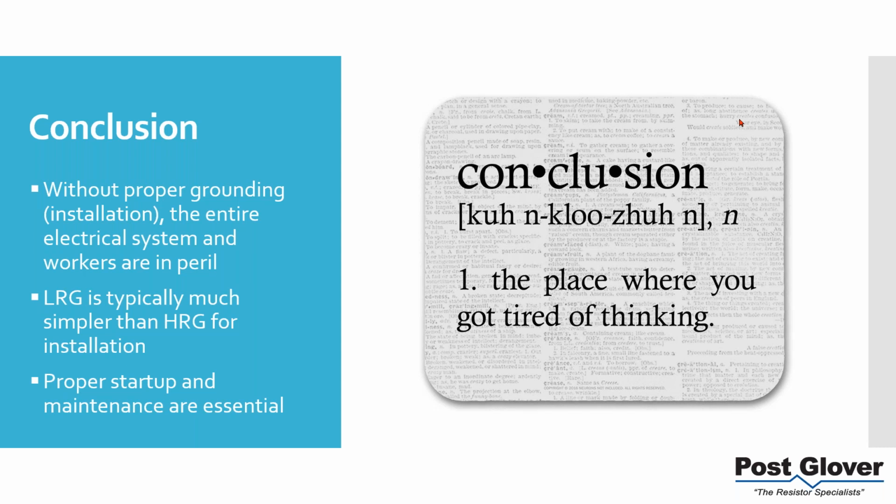We do it internally. To make a very simple version of it, we're measuring resistor current. We're measuring values across both the resistor and the test resistor, and we're basically taking what's left over and saying this is what the charge current is. I don't have the formula, but basically you have a total overall system current and a resistor current, and the difference is the charge current.